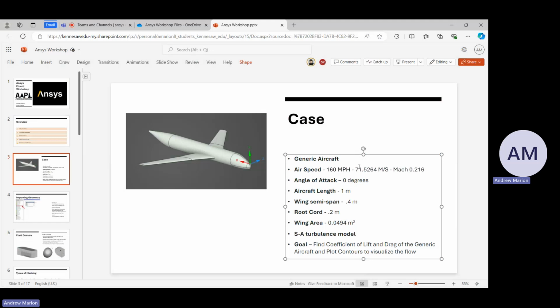Some aircraft have them. Most modern wings have very complex geometries where they won't have an incidence right at the aircraft root, but as the wing goes out, it'll twist either up or down to create an incidence at different parts of the wing. Wing geometry can get very complicated if you want to get really nuanced. A Cessna 172, for example, has a couple degrees of incidence to help it take off in a shorter distance.